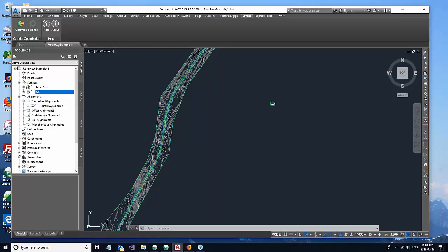I'm also going to go through a process of trying to get the corridor, the sub-assemblies and assemblies out of Civil 3D and bring them into the Softree Optimal environment. That will save me having to recreate them in Softree Optimal. In many cases, if you're doing a preliminary design, you might want to create the sub-assemblies, templates as we call them, in the Softree Optimal environment, and then when you're finished, you bring the alignment and possibly the subgrade surface back into Civil 3D. I'll explain that a little more in a sec.